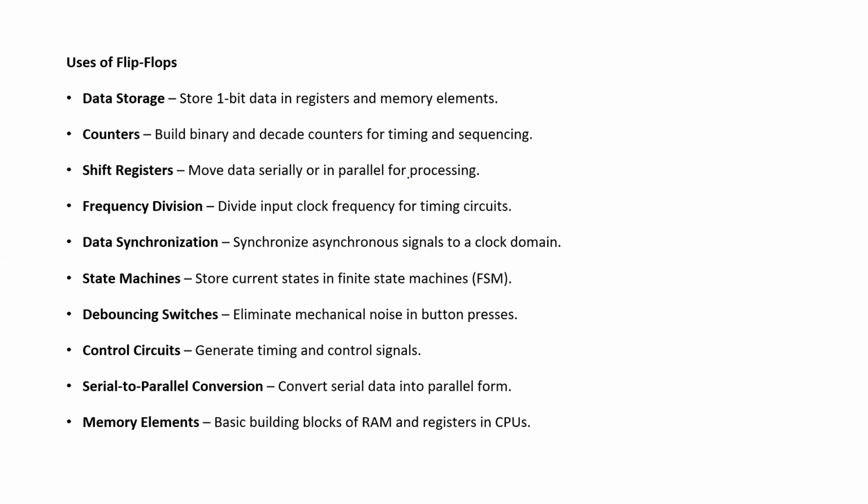Okay, now what are the flip-flop uses? So data storage, actually the main thing, it will store 1 bit of data in registers and memory elements. Counters means build binary and decade counters and timing for sequence. Shift registers move data serially or in parallel for processing. And frequency division, so divide input clock frequency for timing circuits. Data synchronization, synchronize asynchronous signals to a clock domain. State machines, store current states in the finite state machines. So these are the uses actually.